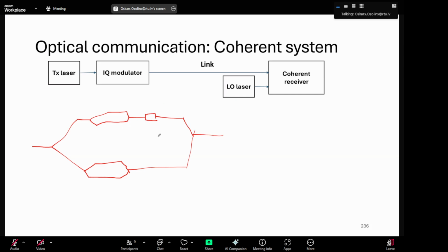So here you need a shift of 90 degrees. You put an on-off keying signal with two levels on one modulator and two levels on the other, and then rotate one by 90 degrees. At the output, you get the 4 points of QPSK.